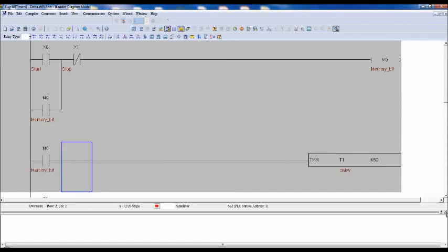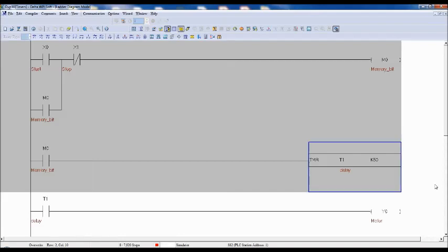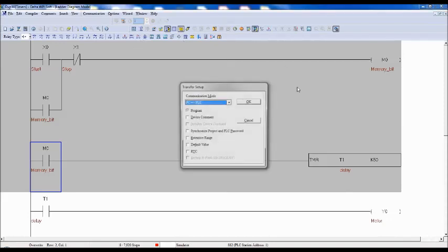See here. First you are going to operate the start button so that the memory bit will be on, continuously on, because there is a holding circuit here. The memory bit goes off by operating the stop button. Whenever the memory bit is on, it is supplying power to the timer. After the delay, the motor is on. Okay, so let us simulate this one.